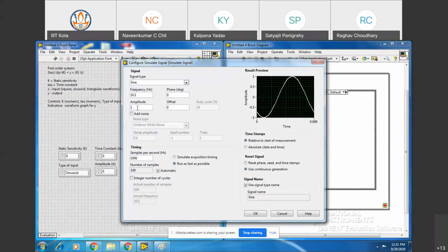So can you see that presently your waveform is moving? That waveform is moving because the number of samples is not a multiple. Suppose I make it 10 hertz. Let's see, it has become stationary. Suppose I take 500 samples per second, and the total number of samples will be 5000. You take an integer number of cycles, right?